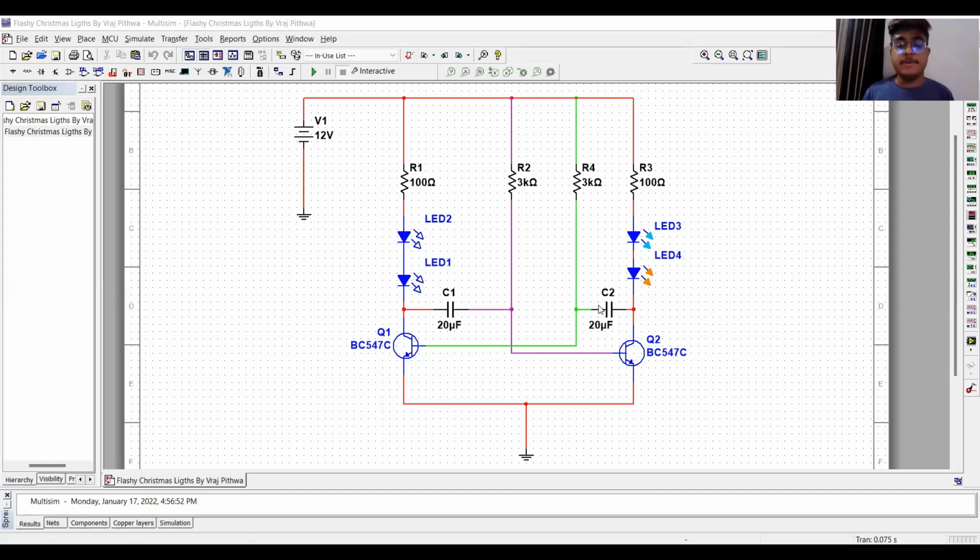Now at the other side of the capacitor, the voltage will become negative. It happens because, let us say our supply voltage is 12 volts. So 12 volts minus 0.7 is 11.3. Therefore, 11.3 is the voltage over the capacitor in the direction of the positive side of the capacitor. Now, when the positive side of the capacitor is connected to ground and the voltage difference over the capacitor remains, the voltage relative to the ground becomes minus 11.3 volts. Because of the negative voltage, the base of the transistor will remain as it is. It means it will not get charged up.